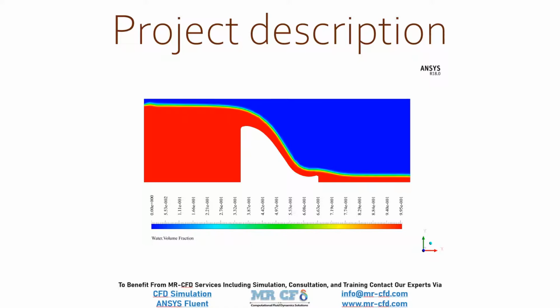Spillways have several types, including open channel, chute, stepped, bell-mouthed, siphoned, ogee, side channel, labyrinth, and so on. The present problem is an Ogee Spillway CFD simulation. Since the channel uses two different flows, the two-phase flow model is used. The two-phase VOF model is used in this simulation so that the water is defined as the primary phase and the air is defined as the secondary phase. The purpose of the present study is to investigate the behavior of water flow after passing through an Ogee spillway in the presence of airflow.